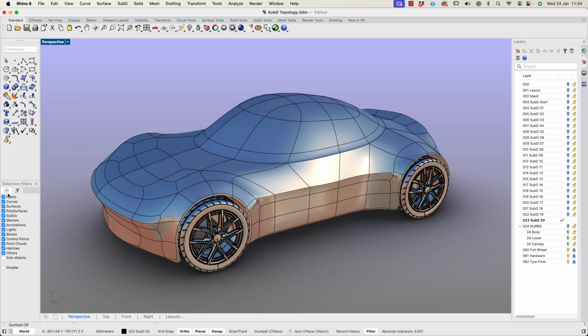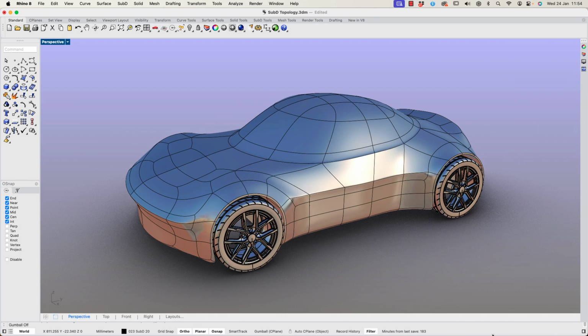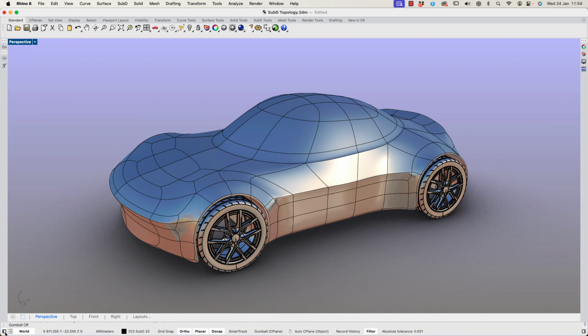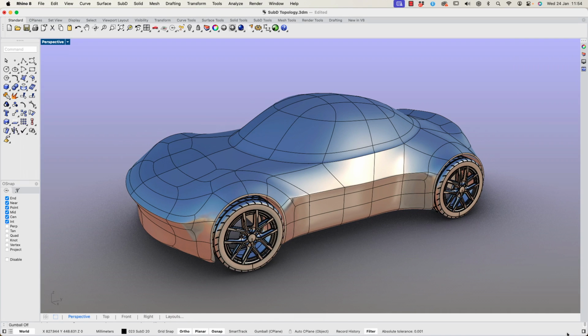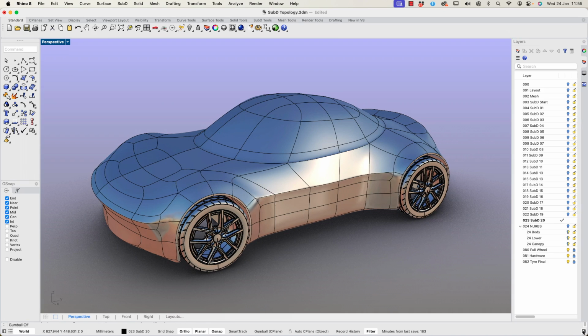Underneath these icons we have tabs for Object Snaps and Selection Filters. The Viewport tabs, Modeling Constraints and Settings for Gumball and History are now all at the bottom of the screen by default. The sidebars can be collapsed by left-clicking on this icon, and this is a quick way of freeing up screen space for modeling. Left-clicking again restores the sidebar.